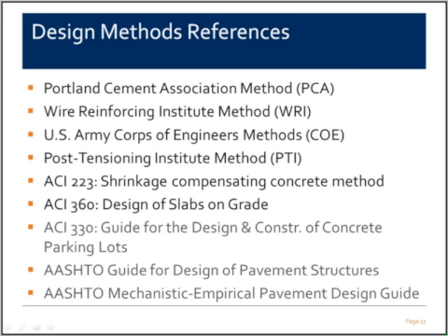I just want to briefly talk about design methods, and the lower three design references are typically for pavement design. It's used for highway pavements or parking lot pavements. The references in the upper, other than the lower three references, are typically for industrial slabs on grounds. And all of these references or these organizations have developed charts of their own and their design methodologies, which you can find at these references. ACI 360 discusses several of these and compiles several of these and discusses it. It's a very good resource.